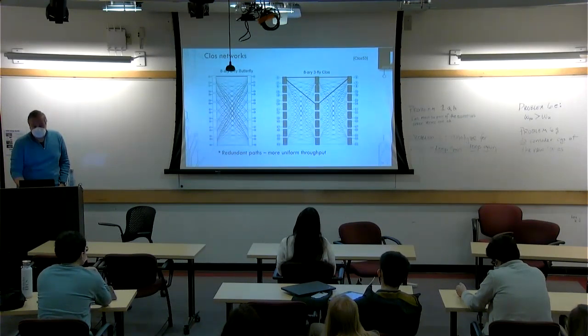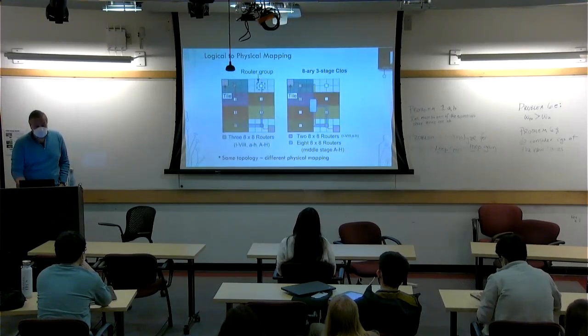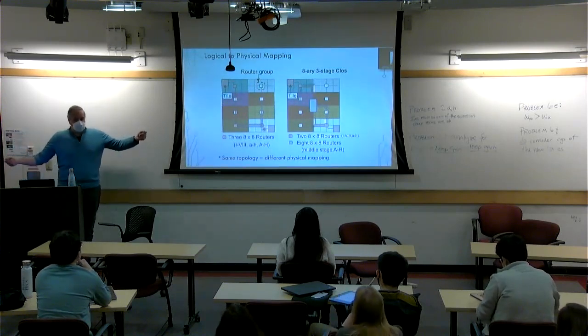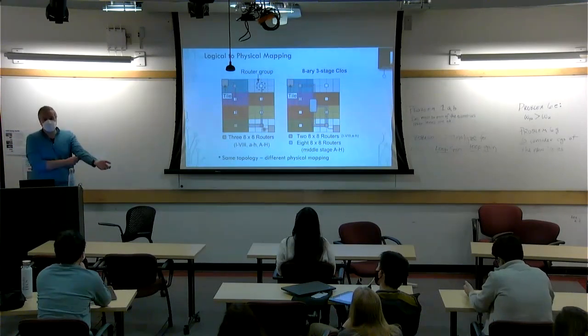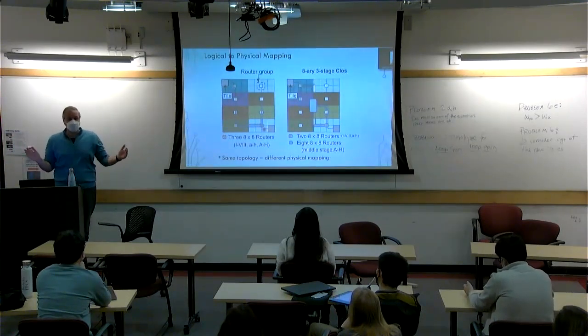So if you put these A, B, C, D, E, F, G, each one of them in each one of these little things, right? That means that my first stage router needs to make it to here, then to here, then to here, then to here, right? And then of course across to all of them, right? So my longest wire is essentially almost the size of the two edges of the chip. That's pretty bad, because it's going to limit all the other wires.